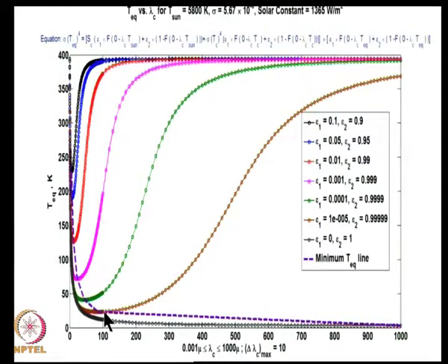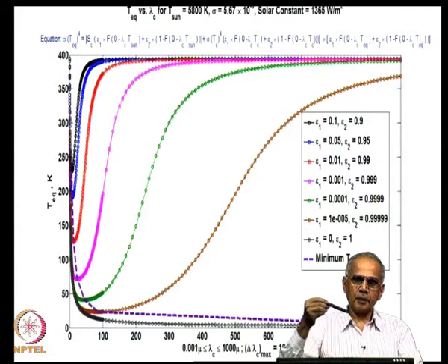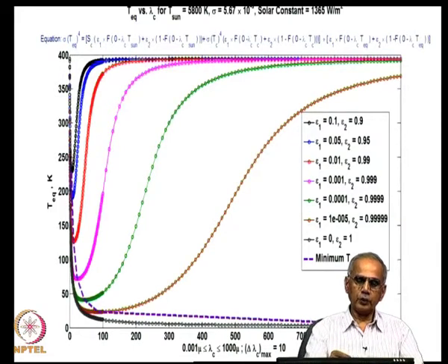At 100 micron, you are able to keep the amount of solar radiation that is absorbed by the surface to a minimum, at the same time keeping the radiation emitted by surface highest. Only when you do that, you get a minimum value which is around here 25 Kelvin.